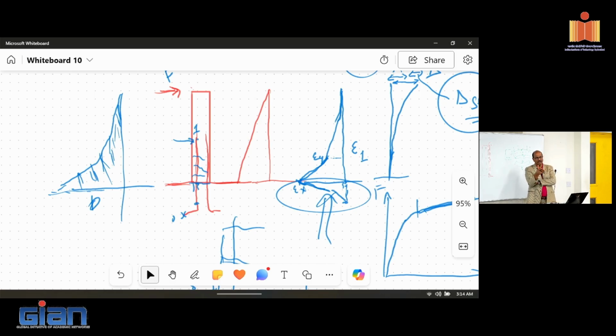As you go back and forth, you dissipate energy and develop hysteretic action. In some of the old textbooks, if you're designing a column, they take the hysteresis loop and back-calculate the equivalent viscous damping, right?